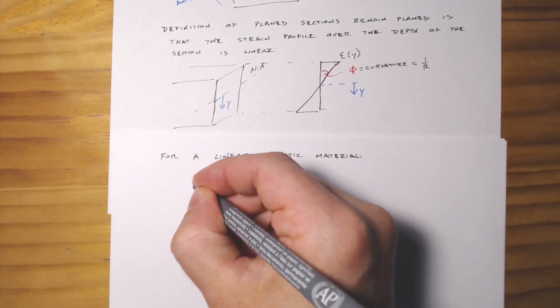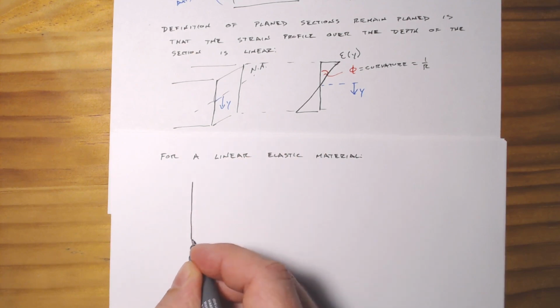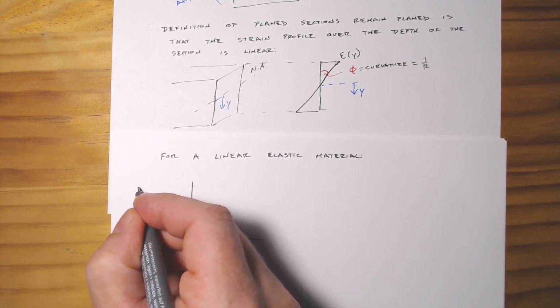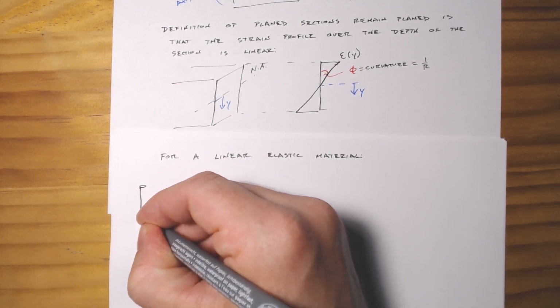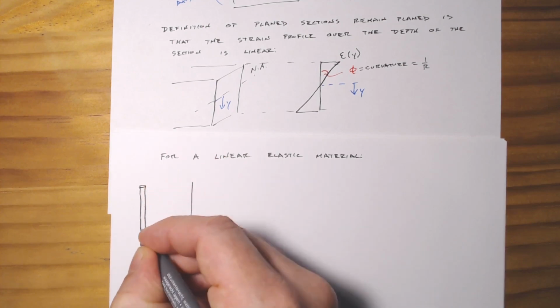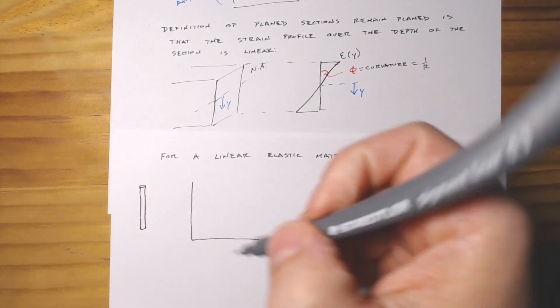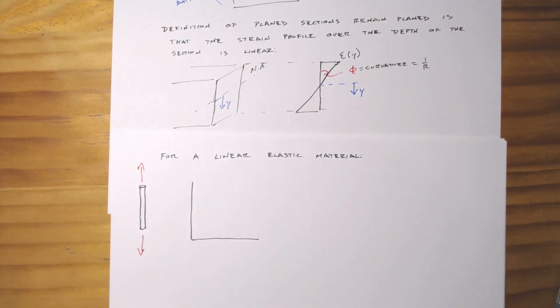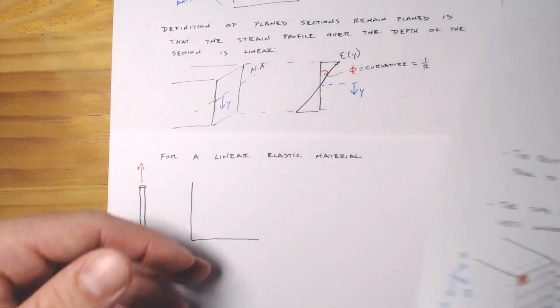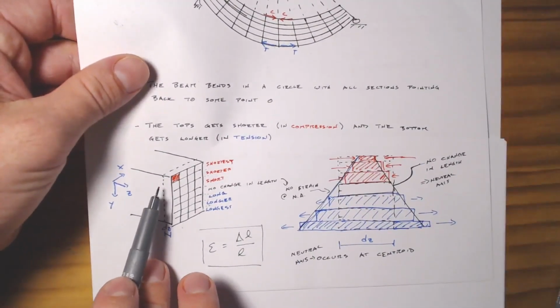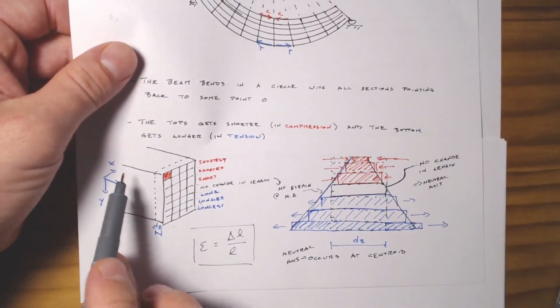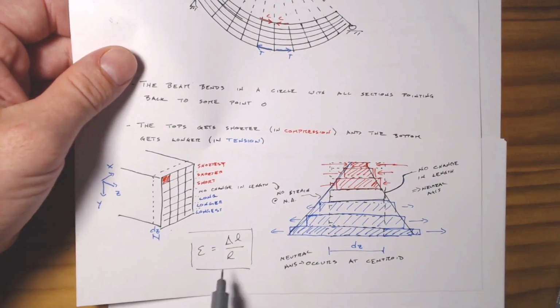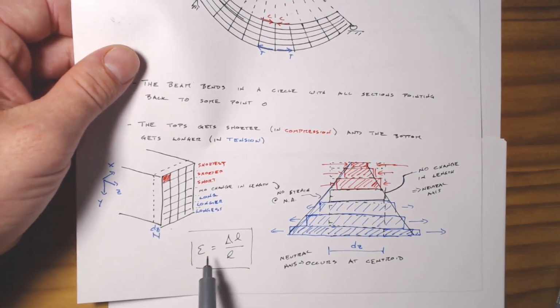So say we've got some axial material, and it'll be pulled in tension. This axial material works out just fine for us because, again, remember, we're just treating each of these little sections like it's effectively a long tube, and we're just looking at its linear strain.